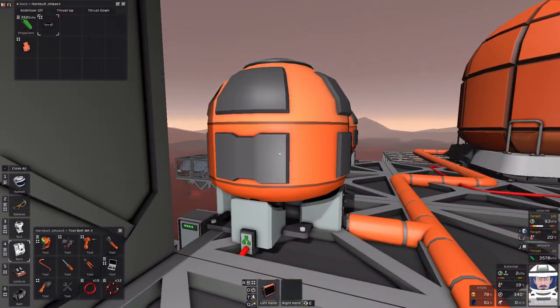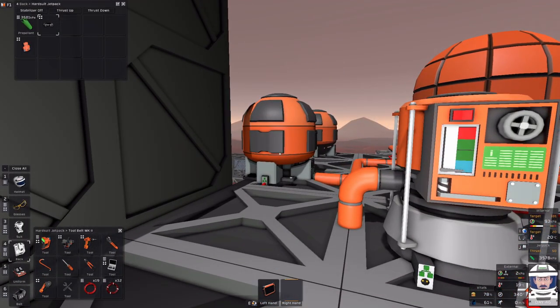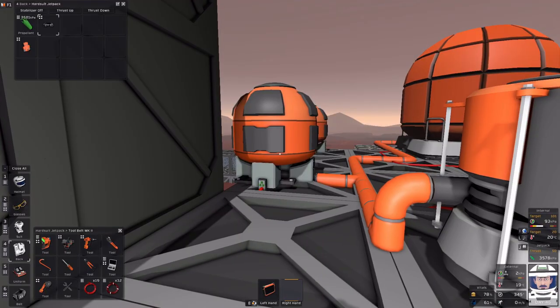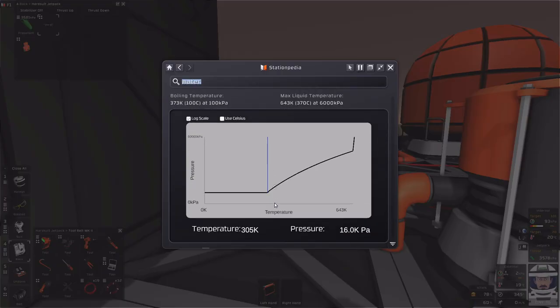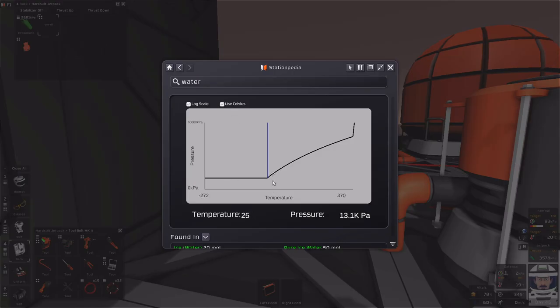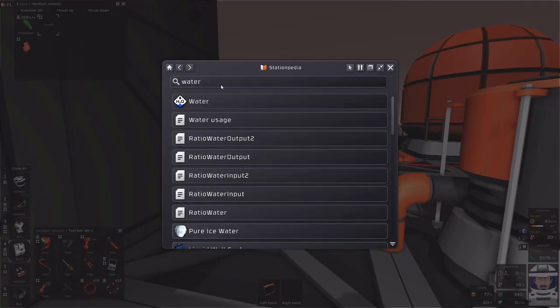So, if I'm going to cool this to negative 20 Celsius, I need to pick a gas that can exist as a liquid at that point. So while I could use water, the issue with water is at 20 Celsius, well, can't use water. My bad. Just thinking 20 Celsius. Can't use water because it freezes below 0. So water is out.